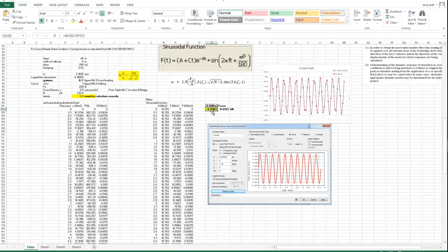Again, if you see here, I have divided it by 3, so I have converted it separately for my 3 stringer beams. As you can see here, this A value is in kilonewton per meter square, so this is a pressure loading, as I mentioned earlier. What the code specifies for the crowd condition is a pressure loading, but we are going to apply it as a point load, so we need to convert it into a point load. As I mentioned earlier, the spacing of my cross beams is 2 meters, and based on the influence area of each stringer, I have multiplied it by 2. I have calculated this for each point on my stringer.